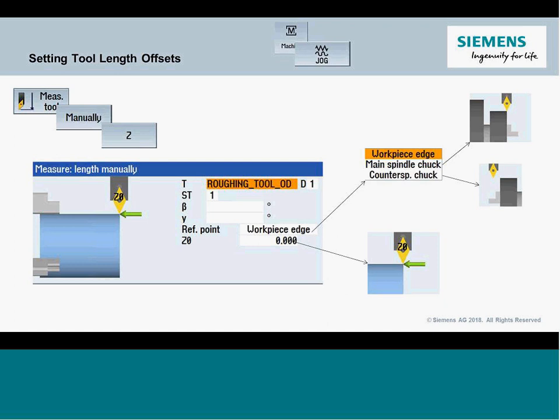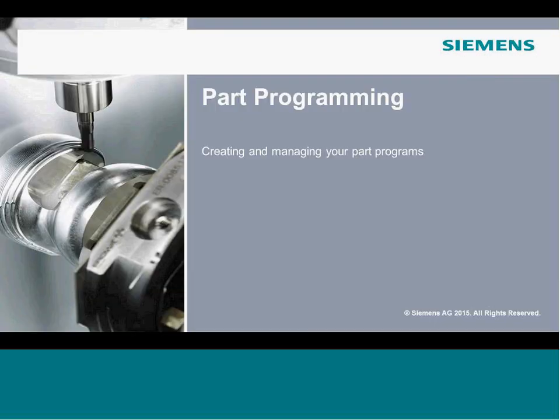If you have presetters, you can just drive up the presetter, and that all gets handled in the back end for you. This would be how I would do it if I want to do it manually on the machine. So now we've got the machine basically set up. We've driven around a little bit, and we kind of get an idea of what's happening from the operation perspective. Now let's look at the part programming.